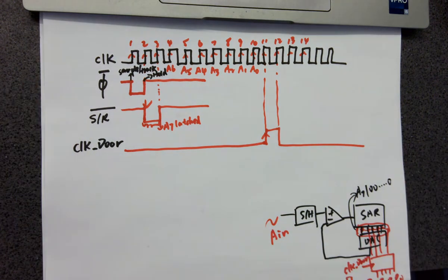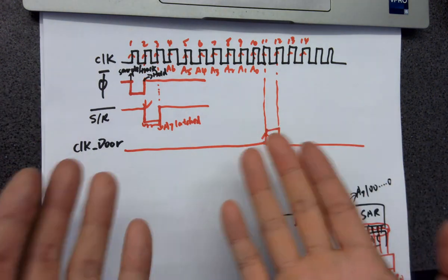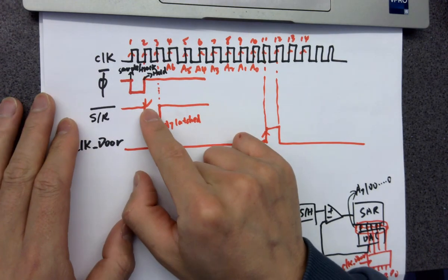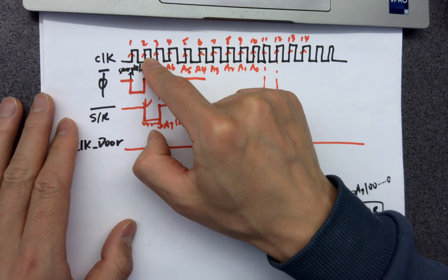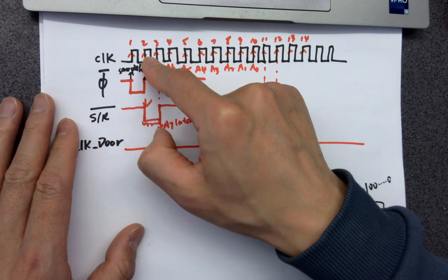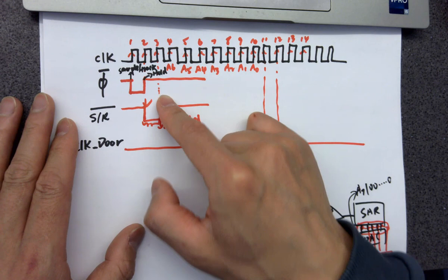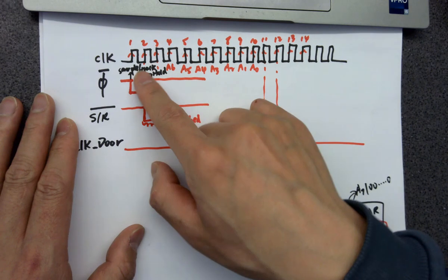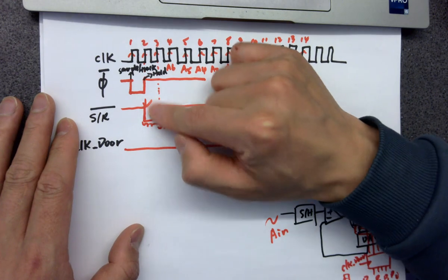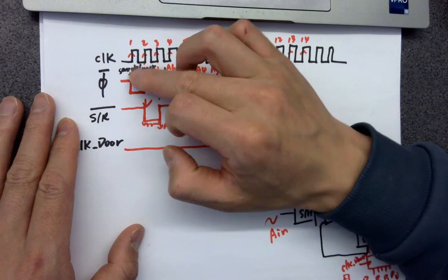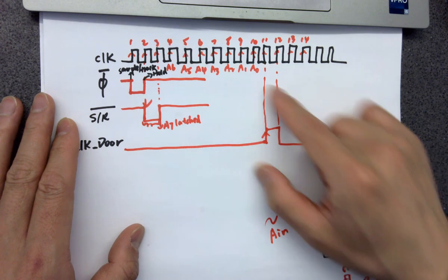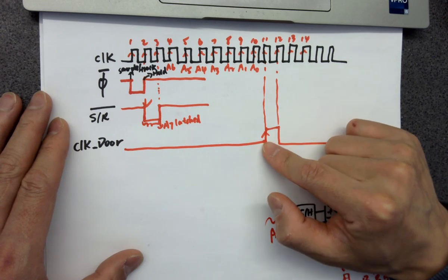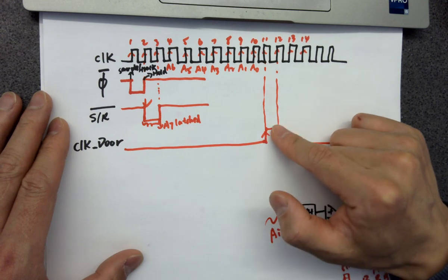So we just request the signal first, and then we know how we can design a circuit to implement it. And the same thing, for this one, I need a rising edge counted at 2. So the counter counts at 2, and then we make a dip. And this one, it counts to 11, and we make a rising edge. So this is pretty simple. All these could be rising edges, which is inverted. So eventually inverted. That's pretty simple. And now, after this clock is done, we need to count to 11 to make a rising edge here, right?